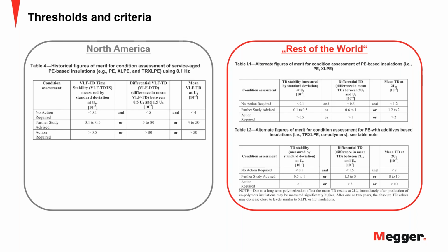Even more so on a brand new circuit, there are companies that have the method to say, okay, on a brand new circuit, everything is done properly. I shouldn't see any PD, period. Because it is correct. If your splice and terminations are properly done, you will not see PD in that circuit. So it becomes much more a problem on service age cables to interpret these levels, because you will have levels, and then it becomes a question how to interpret them.